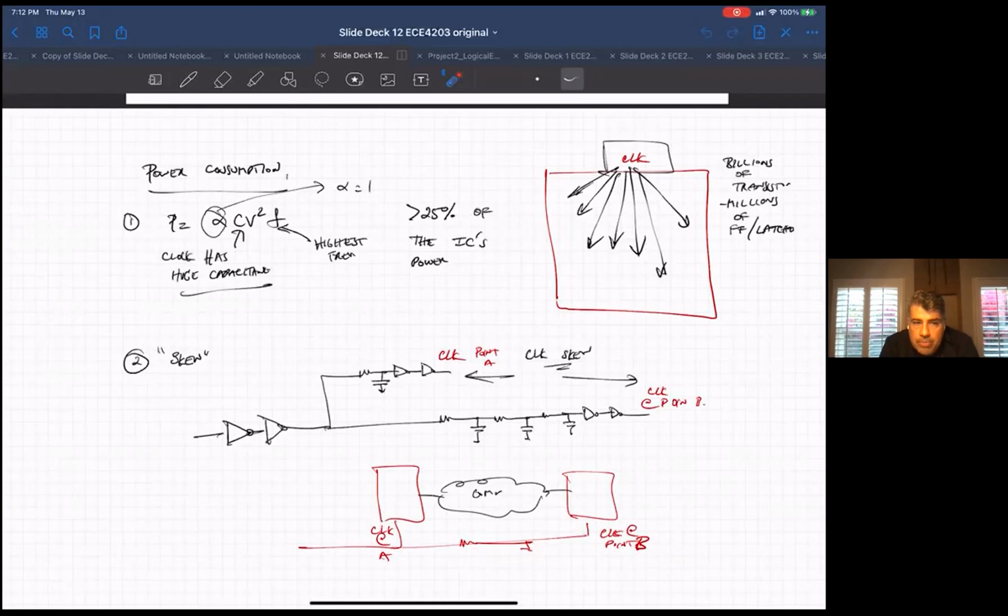at the same time. But the reality is that the clock is physically distributed on your chip or FPGA or wherever, and there are short routes and long routes, and physically it takes a while for the clock to get there if you're at the very end of the chip. We haven't had a chance to talk about clocking networks, but it could be other places on your chip too.